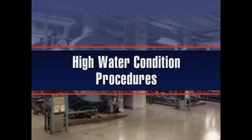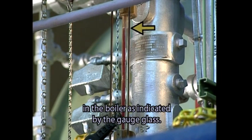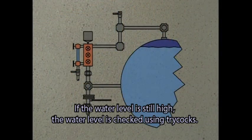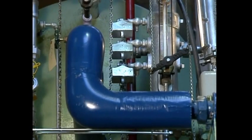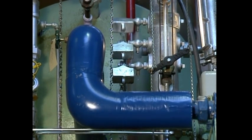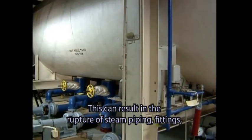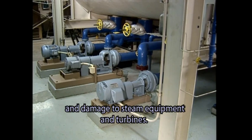High water condition procedures. A high water condition occurs when there is an excessive amount of water in the boiler, as indicated by the gauge glass. The gauge glass should be blown down to assure an accurate reading. If the water level is still high, the water level is checked using tricocks. Water discharging from the top tricock confirms a high water level in the boiler. The immediate danger with a high water level is the possibility of carryover of water in the steam. This can result in the rupture of steam piping, fittings, and damage to steam equipment and turbines.